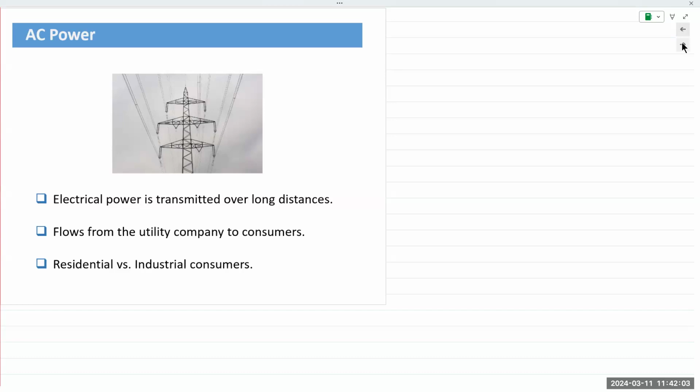Every time electrical power is transmitted over long distances, a lot of that power is lost as heat. If you think back to chapter 1 on the first day of class, I mentioned that resistance of a piece of conductor or a piece of wire is negligible. When you perform theoretical analysis, all electrical wire has 0 ohms resistance, right? But in real life, a wire has resistance, it has inductance, and it also has capacitance. Resistance mathematically is given by the equation rho L over A.